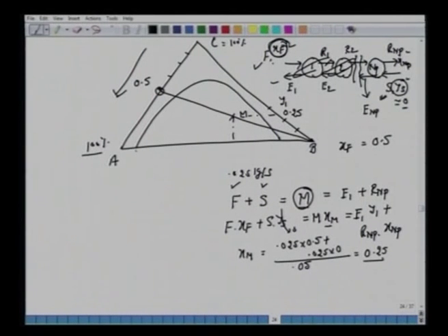All right, now XNP is also given to us. This XNP is 5%, a very small amount of solute in the treated raffinate. So again, go to the scale of AC. A is your feed raffinate, and C is the solute. So C is 100% here, and we are looking for 5%. Then you have to get down to this level. Maybe this is 10, so you're going to read 0.05 here. So this is RNP or XNP.